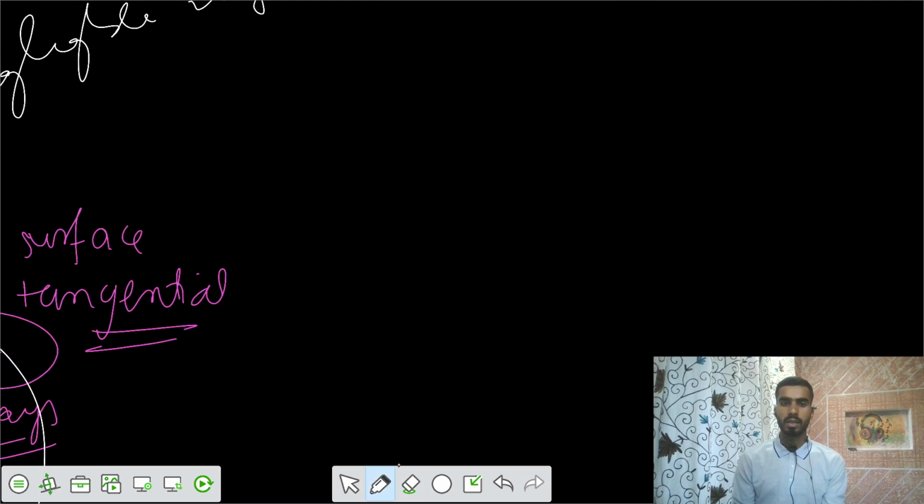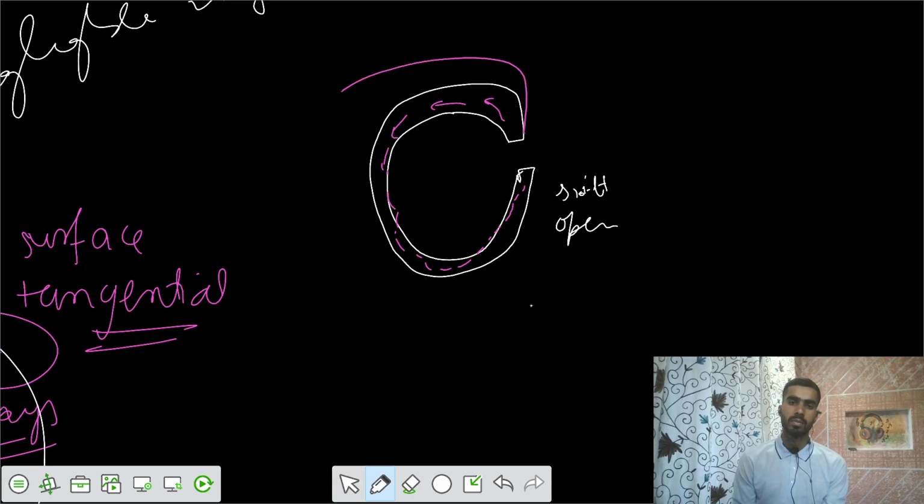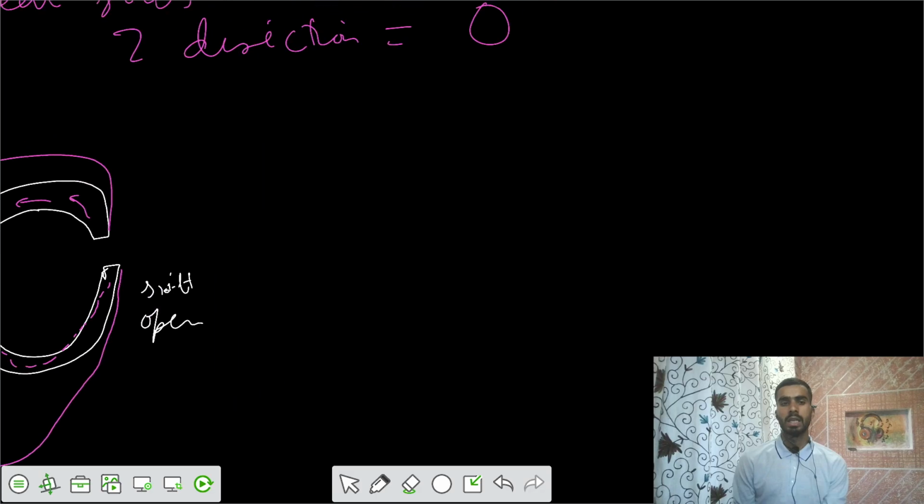And if you have that same circular section, but there is some slit, some opening on the side, from one side of the periphery we have this part that is opening. We call it a slit. So the shear flow variation would be in this way. Let's say this is some shear flow variation. So based on this, this is some variation of shear flow or shear stress. So you got this one.